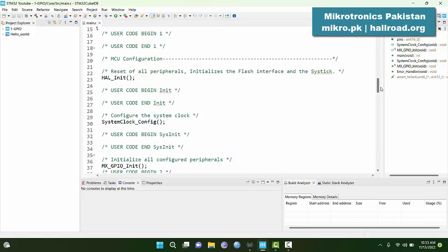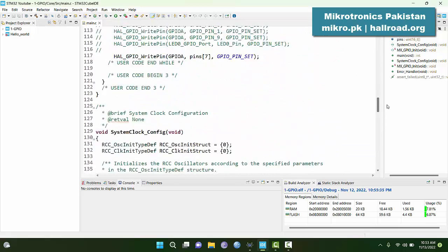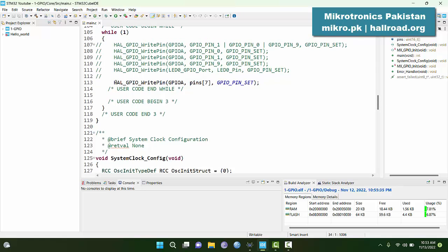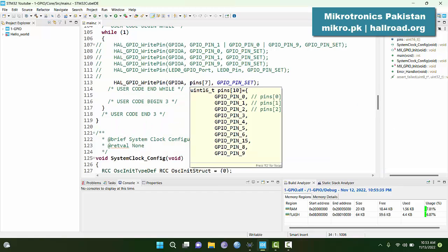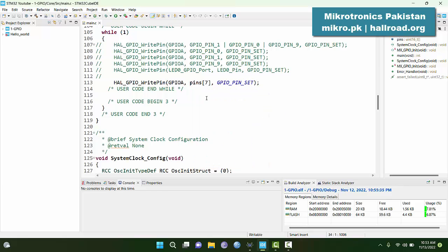And then you access those pins using your HAL function, but instead of giving the pin number, you give the reference to the array, and that will access the required pin. Now, in order to make your code more organized and more structured, it is a good idea to make the code abstracted from the main usage by putting them into functions.